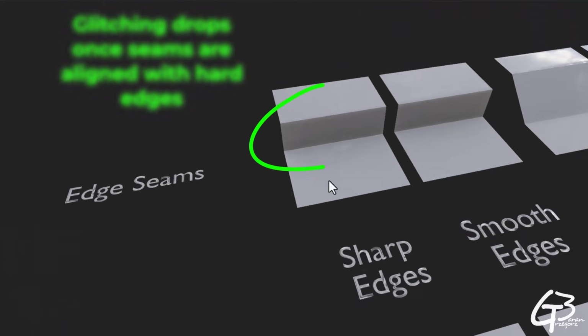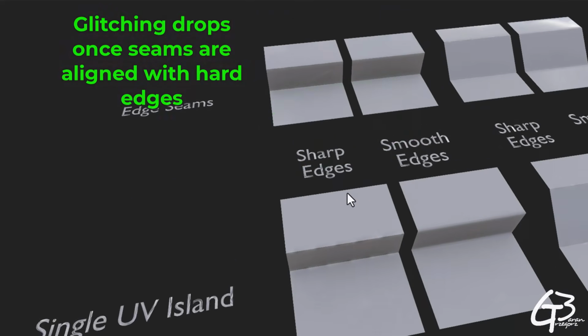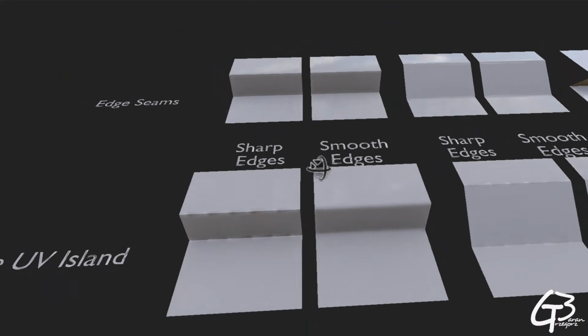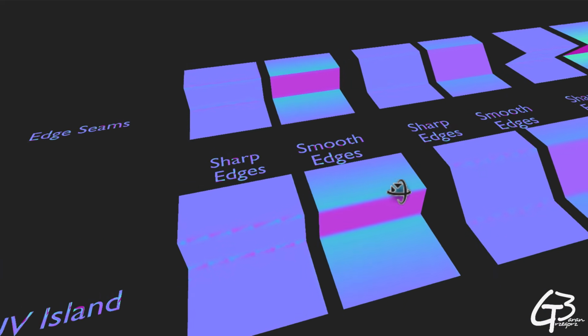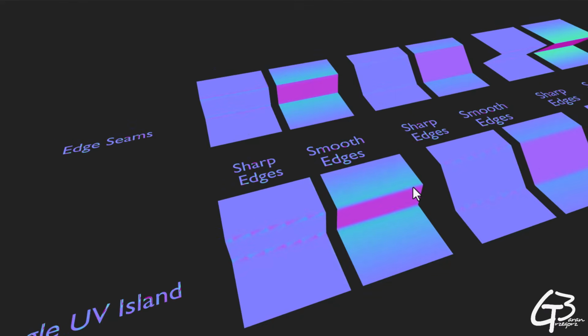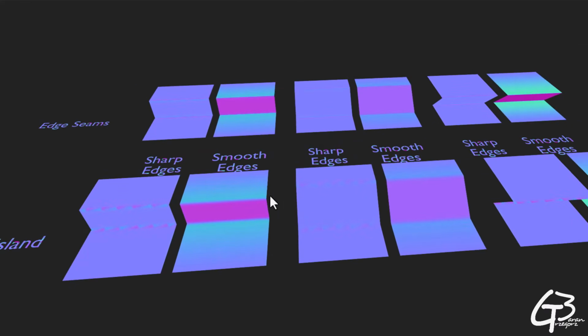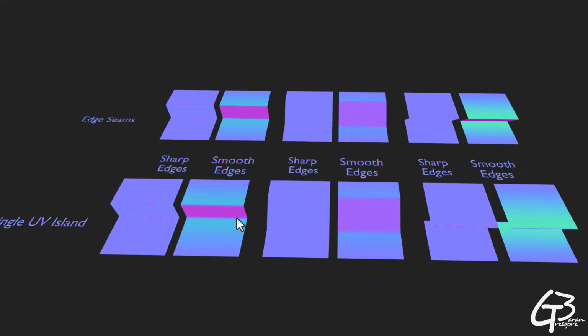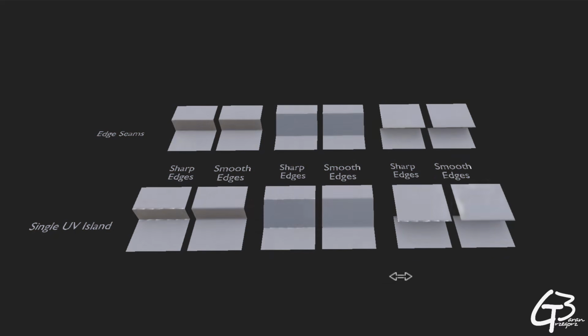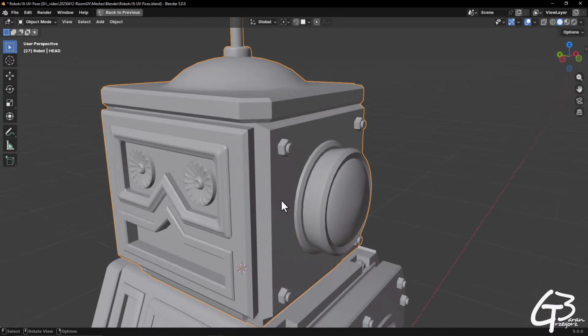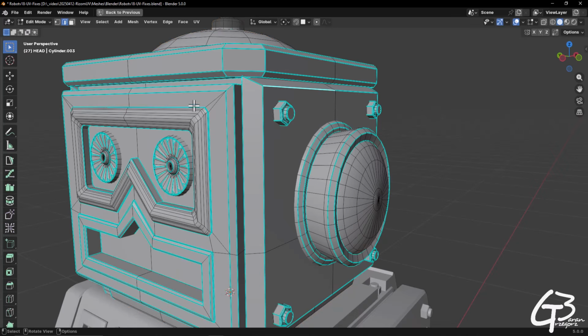From a technical point of view, once a vertex is split, either by a hard edge or UV seam, it's duplicated in the vertex buffer. Stacking both doesn't add much extra cost beyond the first split, so pairing them is barely noticeable from the memory point of view. So always pair hard edges with UV seams, while for organic models, use seams where needed for distortion control. But keep normals smooth unless there's a visual reason to break them.